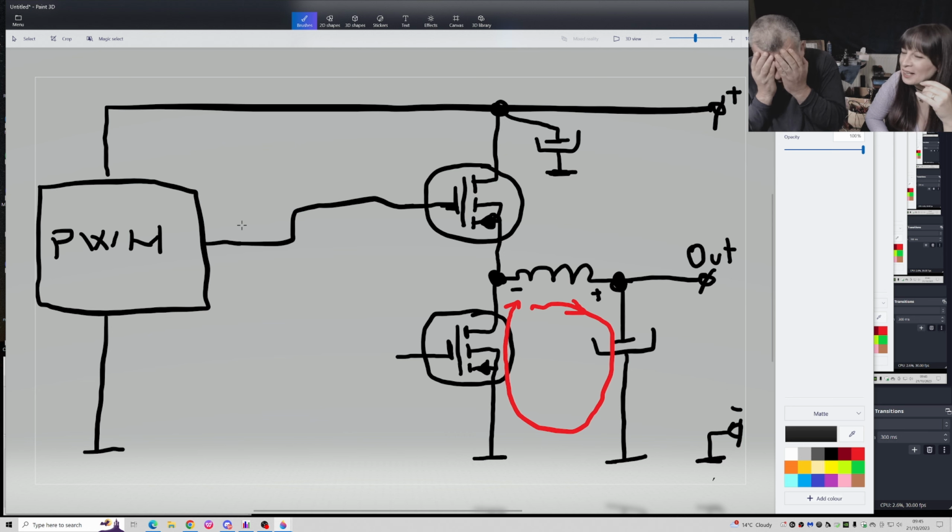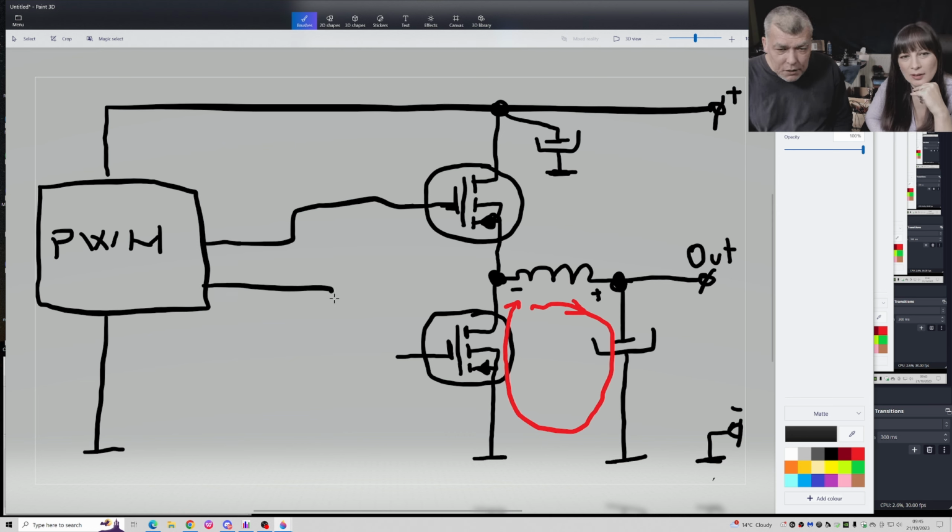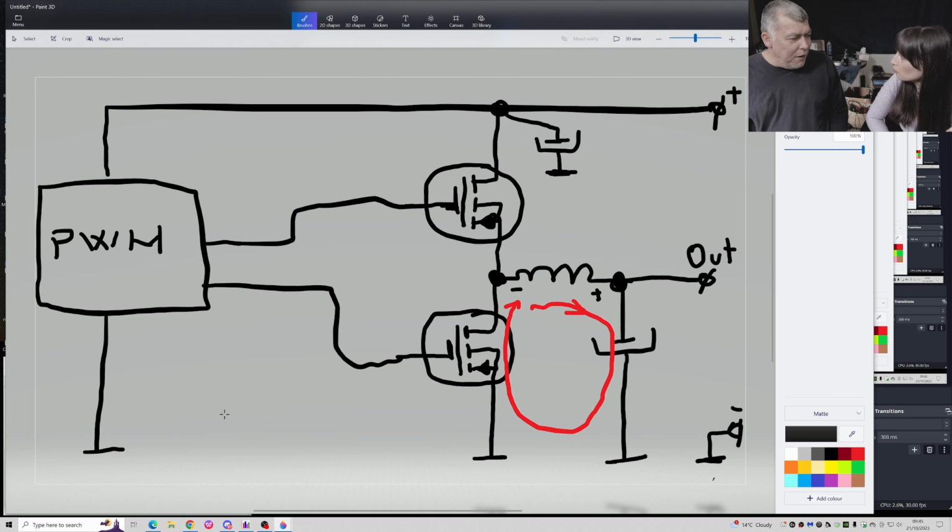Oh, you know what? I hate when people tell me to use a chip. What's the point of having something else? It's stupid, it's pointless, when you can have two outputs and connect one to that MOSFET and one to the other MOSFET. That's how you will find it on Google. But it's not simple, because it forces you to use a specialized chip IC, something special for this power supply. I don't want to be forced. I want to be free to use any PWM generator.